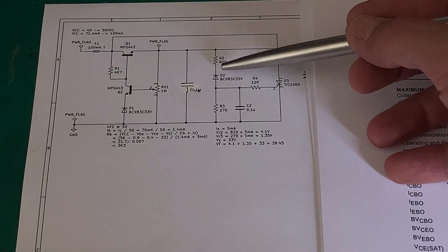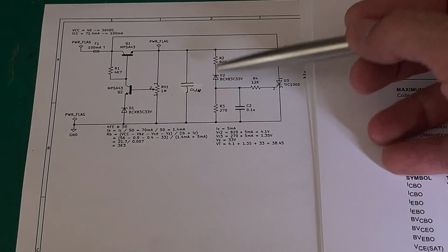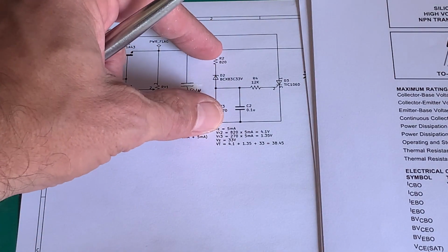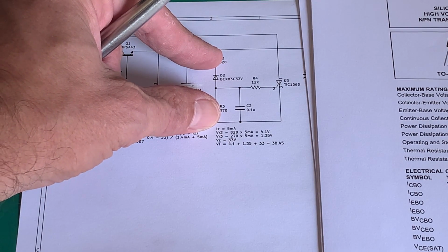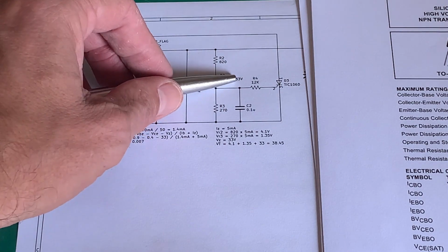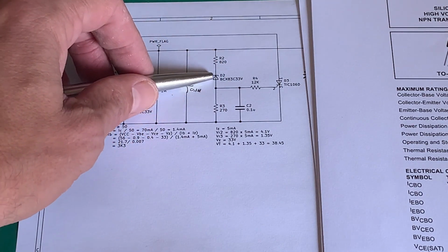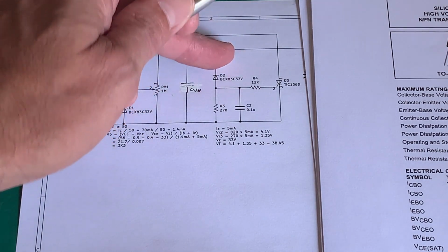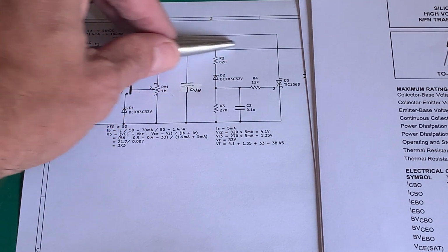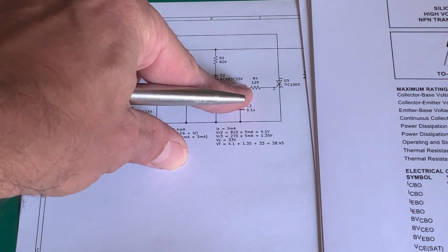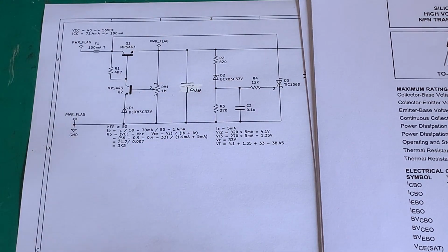And we're already familiar with the Zener diode. By just changing the placement, forget about these two resistors at the moment. If we don't worry about that, that Zener will have a voltage reference. So that means the voltage there, well, if that resistor wasn't there, would be the same voltage as that until it gets to a point, and then the Zener will start passing current.